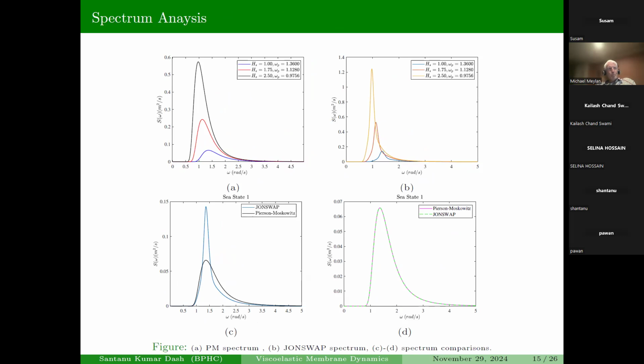And if we look at these zones of the spectrum, it will eventually be larger than the Pierson-Moskowitz. So for the real case also, if you just look at the comparison I provided in the figure, JONSWAP, with its peak enhancement factor, makes it a narrow-banded spectrum, where for a short duration the impact of the waves will be higher within this range of omega.